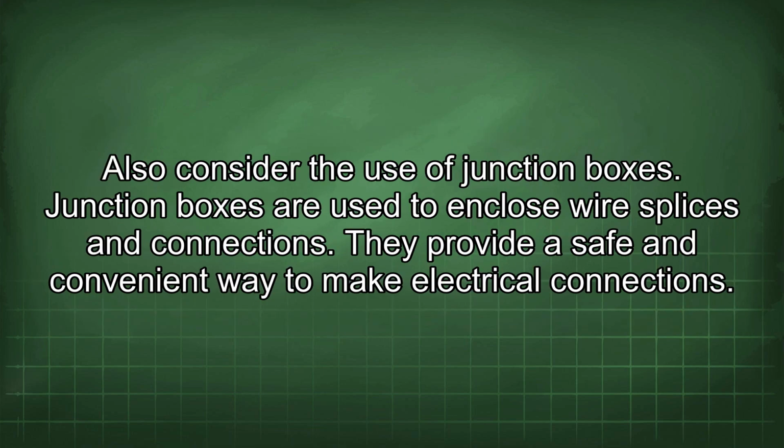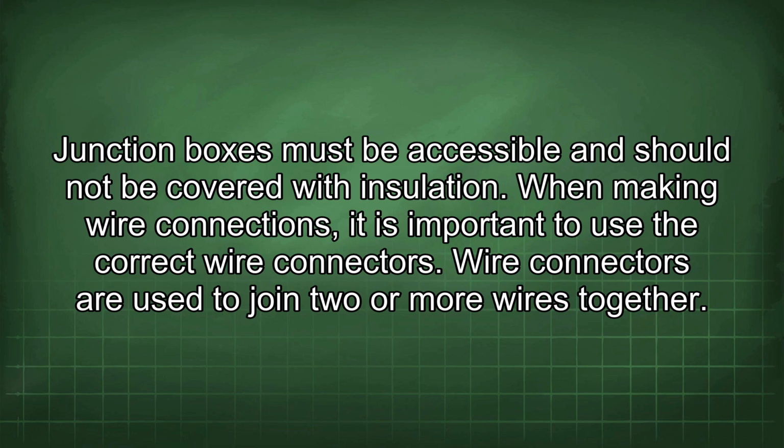Also consider the use of junction boxes. Junction boxes are used to enclose wire splices and connections. They provide a safe and convenient way to make electrical connections. Junction boxes must be accessible and should not be covered with insulation.